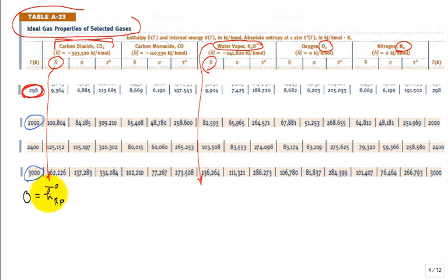We're going to have the 3 times. Now, I have to pick something. I'm going to pick for the first one that it goes out at 2,000 Kelvin. I just have to assume that because I have to iterate. There's no easy way to use this table without iterating when I don't know the temperature at which I need to get the enthalpies.